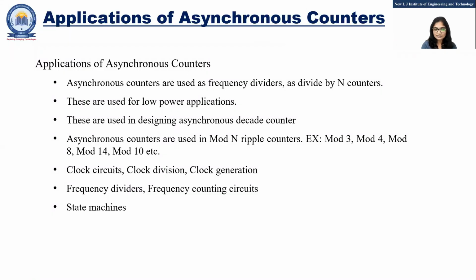These are the applications of asynchronous counters. As I told you, we can design mod 3, mod 4, mod 8 counters, meaning whatever count we need, we can design the counter this way. Then we can design a decade counter using this asynchronous counter. Then we can use these counters in frequency dividers, frequency counting circuits, state machines, and in clock generation and clock division also. These are the applications of the counters.